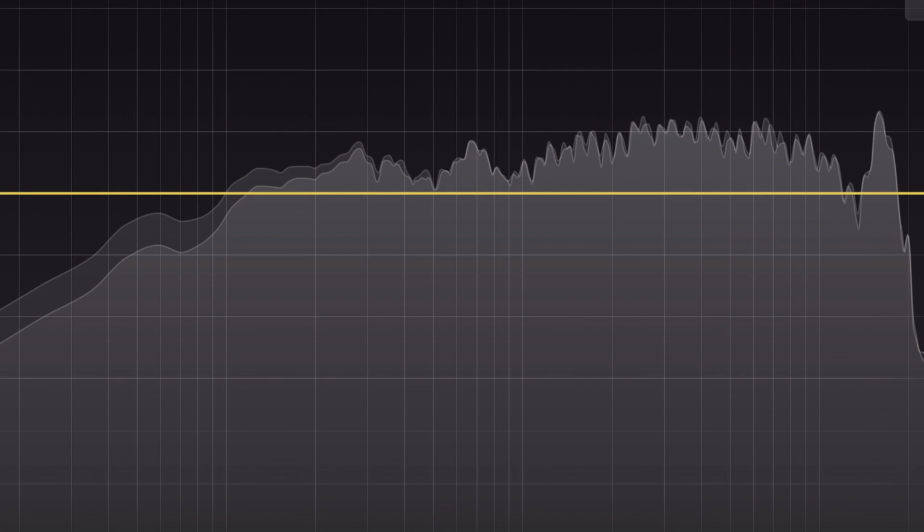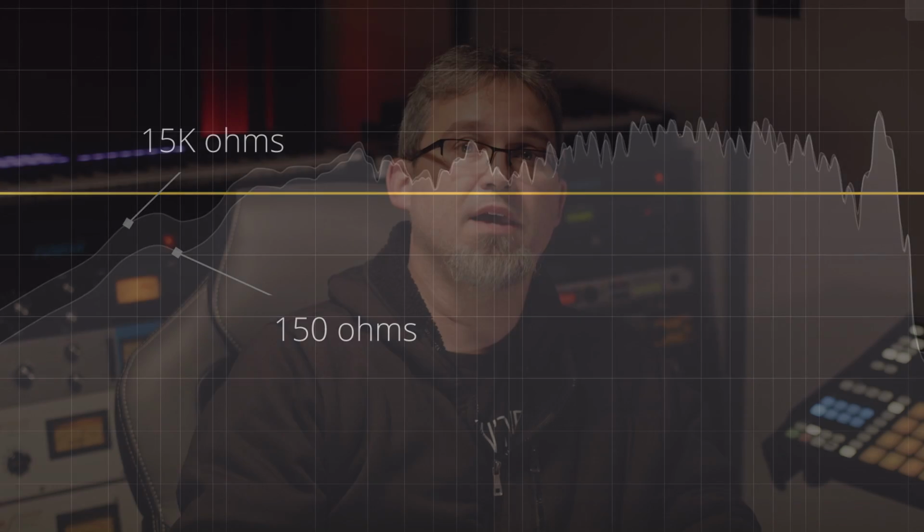In reality, we checked all of the marked settings on the CLZ as we did with the other tests. But between the 150 ohm and 15K ohm settings, we had a significant change in the low end, around 8 dBFS in some spots. The high end showed no considerable change, so I'm going to say based on this information that there is some credibility to the claims in the lower end of the spectrum, but the higher end is not significant enough to care about.